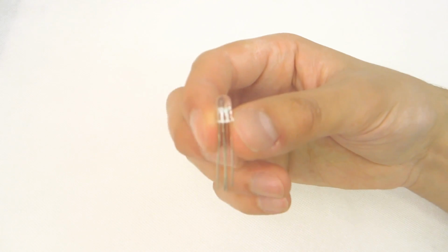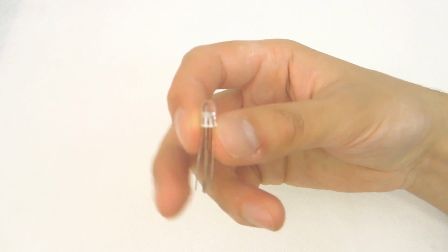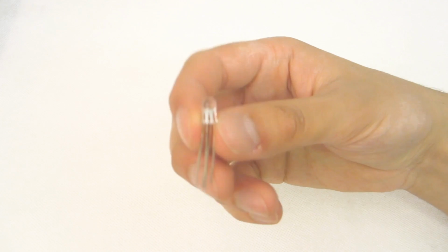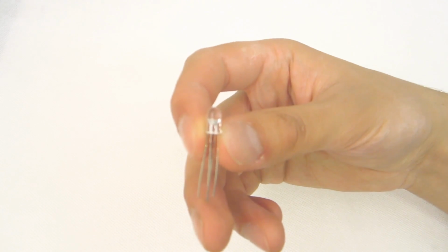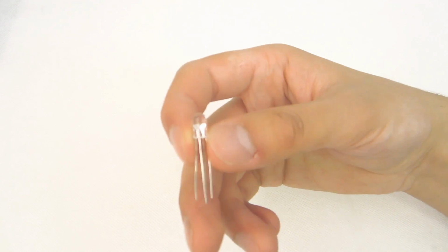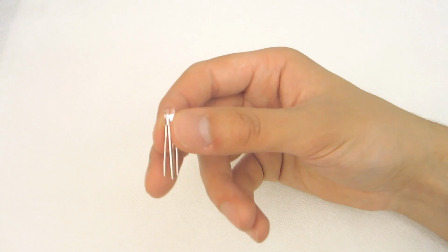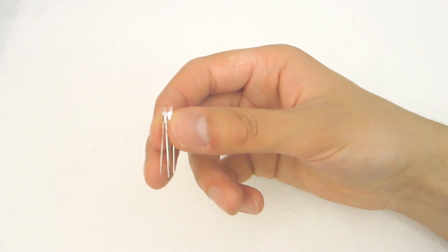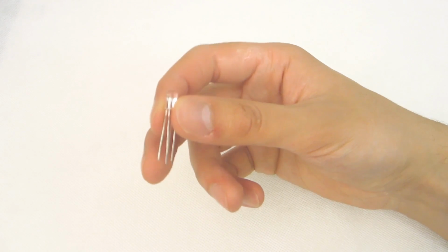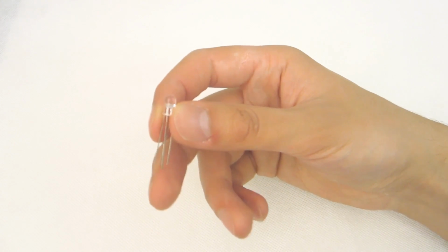And the 3 terminals, we have 3 anodes, 1 for each color, and the long terminal, or the cathode, for the negative power supply. So we have 4 terminals, the 3 shorter legs, anodes for the red, green and blue, and the longer cathode for the negative power supply.